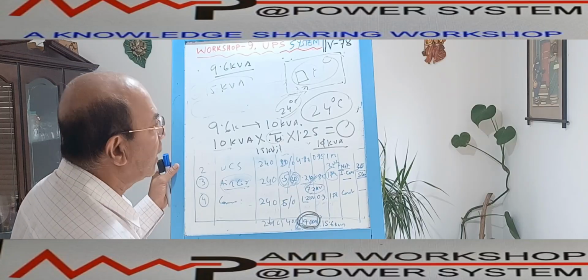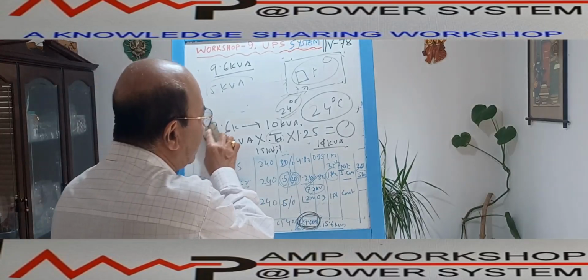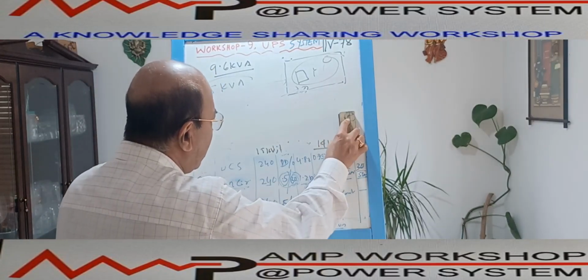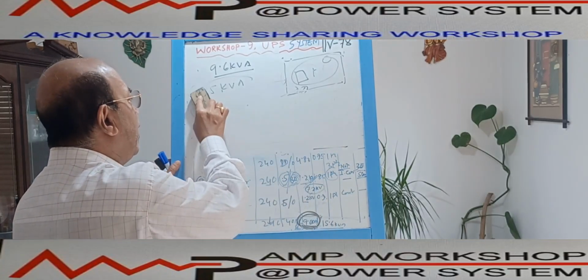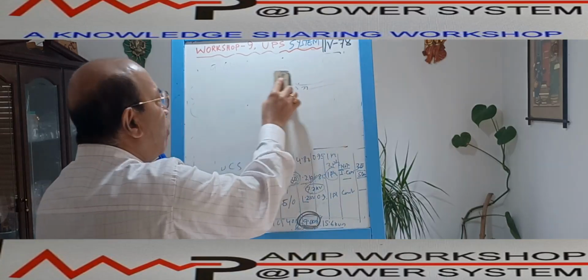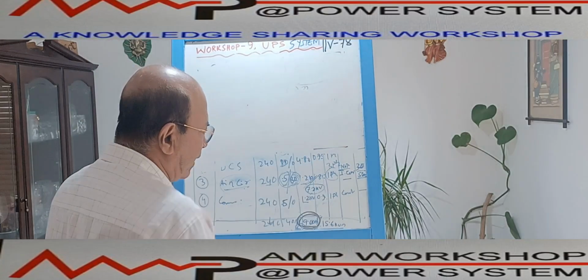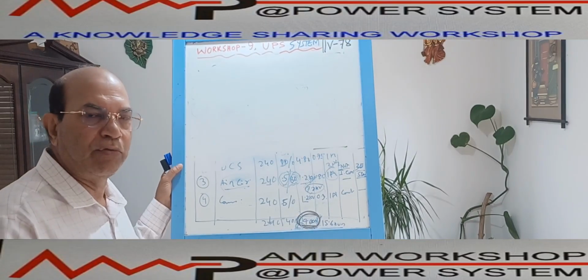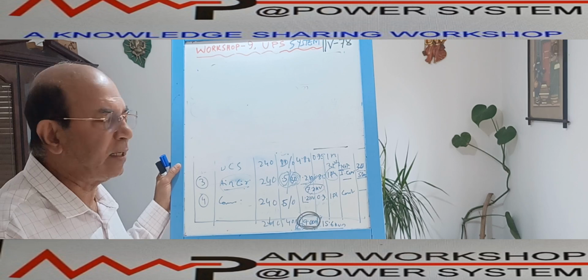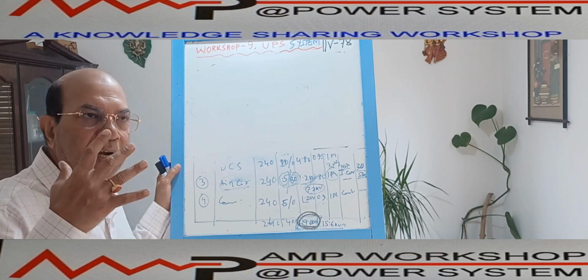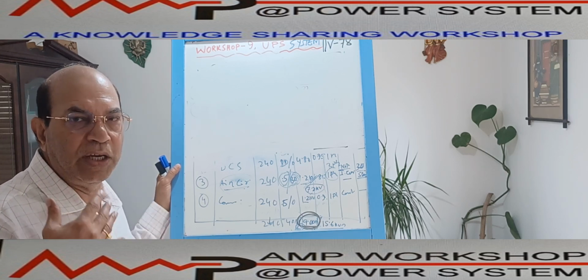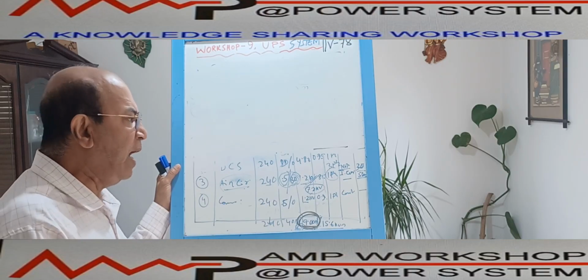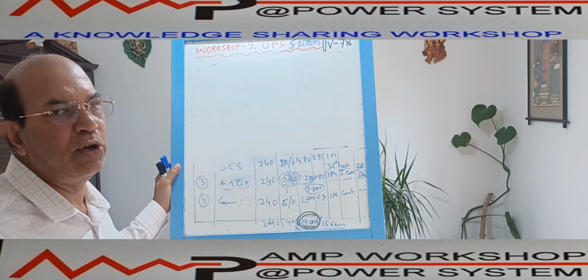Now consider the load is not steady state, it is a transient load. If it is a transient load, then it depends on the sequence of operation. If this transient load or this inrush load is required only one time during startup, in that case the additional inrush current or inrush kVA required during startup, I need not incorporate in the UPS system.